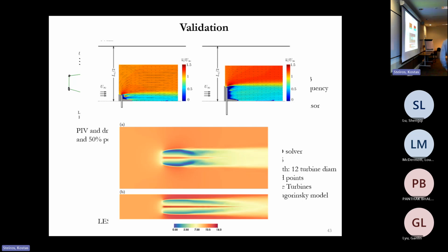It's more red, right? Something similar happens here with the wind turbine. Here we have the wind turbine, but then what we do is the opposite problem. Instead of increasing the wind turbine, we decrease the domain size, and you can see here that the shear decreases, right? So this is the flow as it goes downstream past the wind turbine.